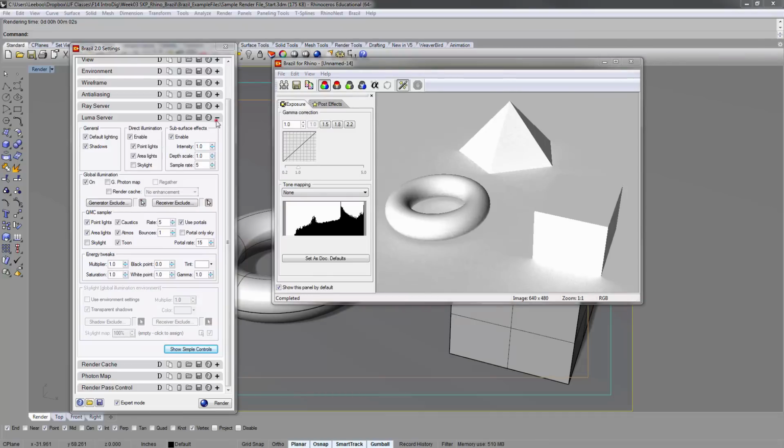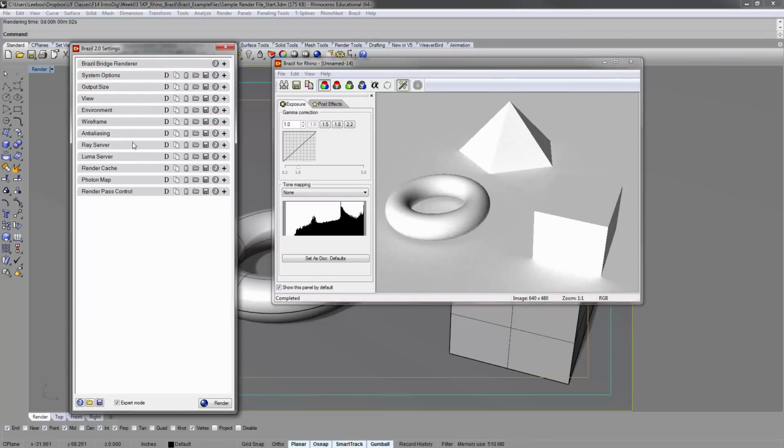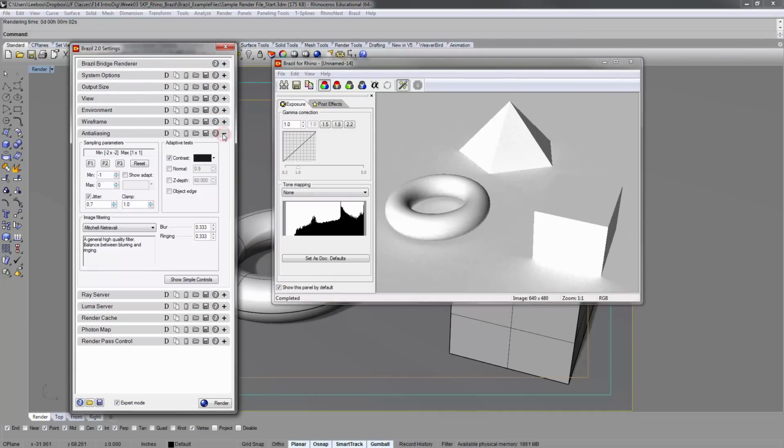Now this is just to show you some of the quality settings, basically in here, the anti-aliasing. These are settings that control the most basic quality settings. The higher they go, the longer your render times will be. So P1 is basic, the lowest, and this goes higher and higher. It's a range between the min and the max. If we do P1 and render, you'll see that things get blurred out, right? The quality isn't high, but it was a lot faster.